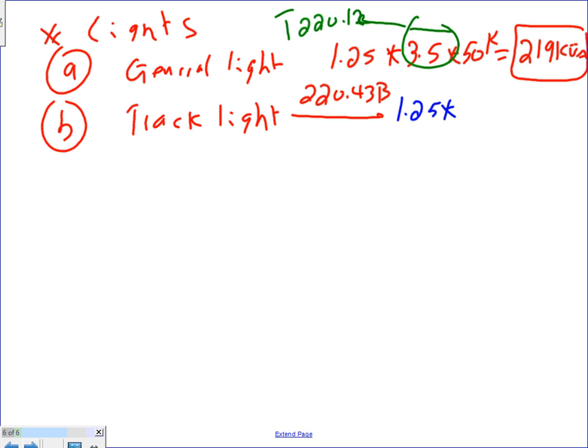All lights are continuous load. 200 because that's how many feet we have, multiplied by 150 from the code, divided by 2 because the code says for every 2 feet, give it 150 volt-amps. Cool. And I'm going to make the answer directly in kVA. If you can read my writing, is it 19 kVA or 11 kVA? Anybody did the math on these?